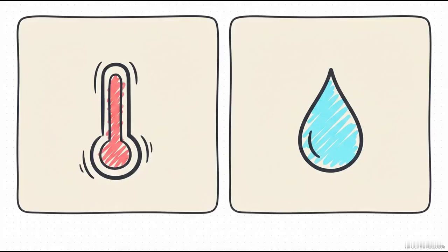But here's the thing, temperature is only half the story. The absolutely crucial point here is separating sensible heat, which is what you actually read on a thermometer, from latent heat, which is the hidden energy tied up in humidity. Sensible heat makes you say, wow, it's 90 degrees in here. Latent heat makes you say, man, it is incredibly muggy. And an air conditioner has to fight both of those battles at the exact same time.